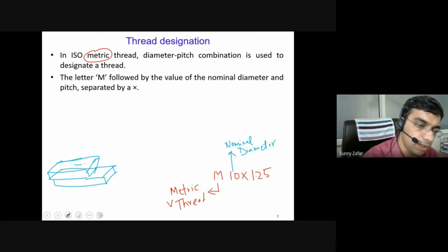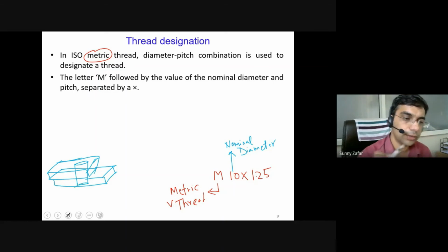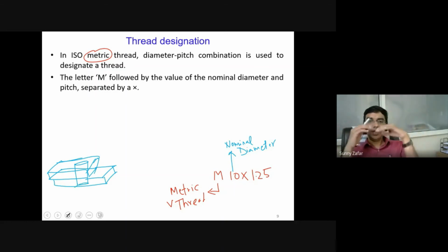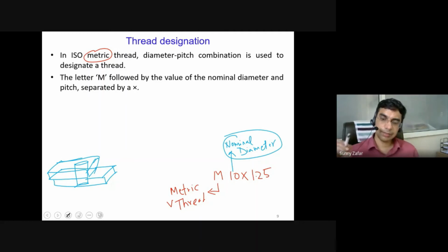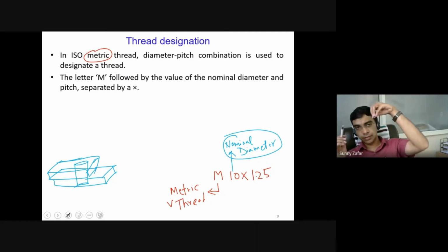So what will you do? First you will drill a hole. As discussed earlier, to place the fastener, you have to drill the hole. Once the hole is drilled, the selection of the drill bit matters, what will be the diameter of the drill bit? That diameter of the drill bit will produce the hole of that particular diameter. So why is the nominal diameter important? The nominal diameter of the bolt or the fastener is important because it will be encasing or filling up that threaded hole.